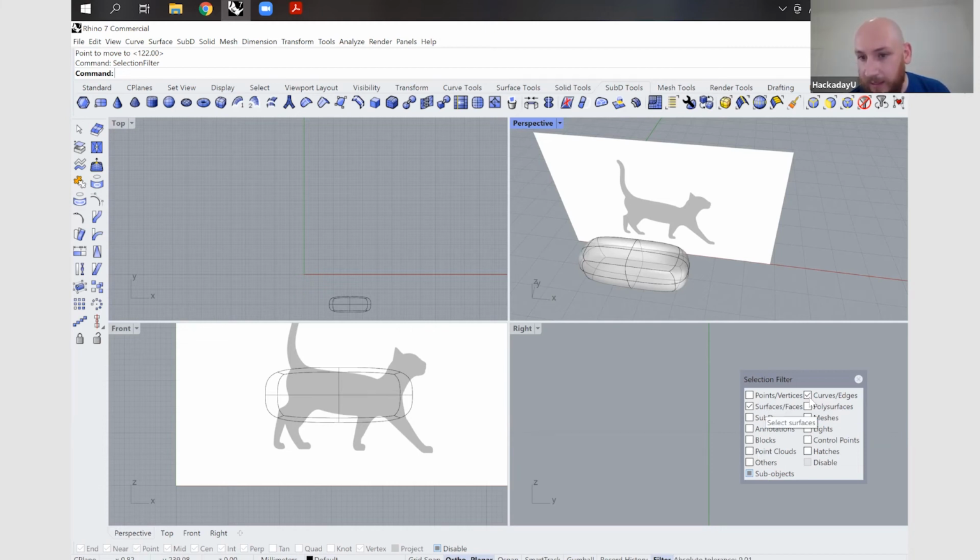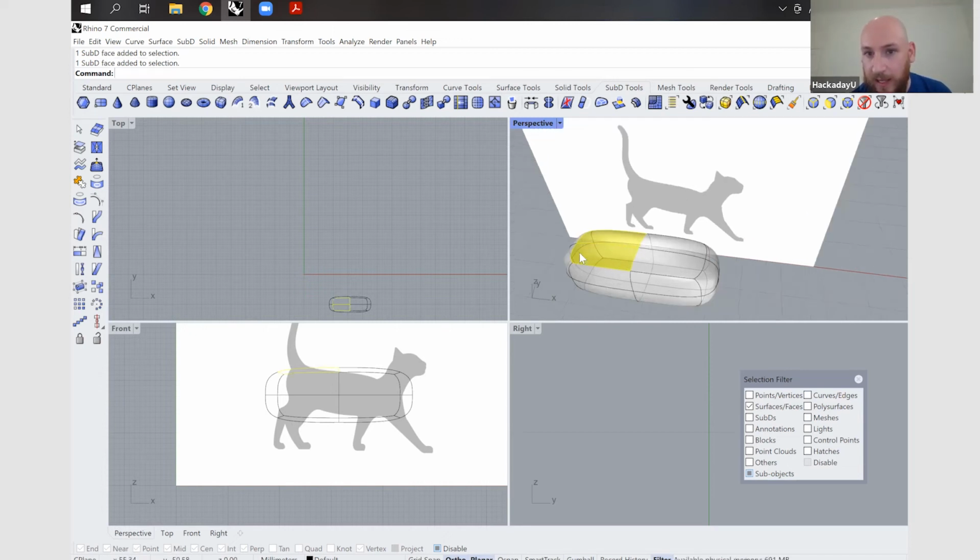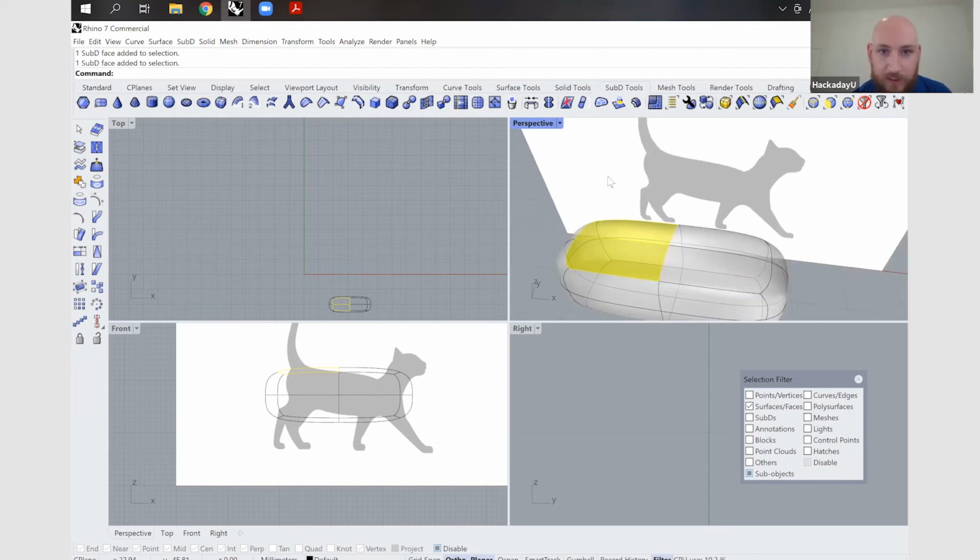These are all on when you start, and you just sort of deselect them all. Now I can only select a face, or turn that off and turn curves on and only select a curve. That's because there's so much geometry going on. I'm going to basically flick these on and off to control what I'm doing. So I'm going to start by only controlling the faces, and hold down shift to select two and select this sort of back part.